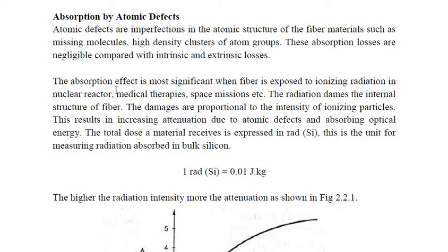The absorption effect is most significant when fiber is exposed to ionizing radiation in nuclear reactors, medical therapies, space missions, etc. The radiation dents the internal structure of the fiber. The damage is proportional to the intensity of ionizing particles. This results in increasing attenuation due to atomic defects absorbing optical energy.